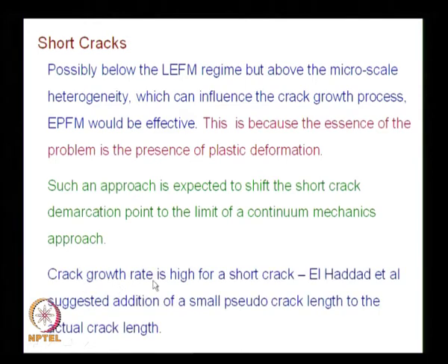Crack growth rate is high for a short crack. So, it is well documented in the literature. People have found whatever the fracture theories, the fatigue crack growth theories which we have developed, they are not applicable to short crack because they have a higher growth rate. And people are accustomed to do certain things in LEFM, they extended similar ideas in handling this situation also.